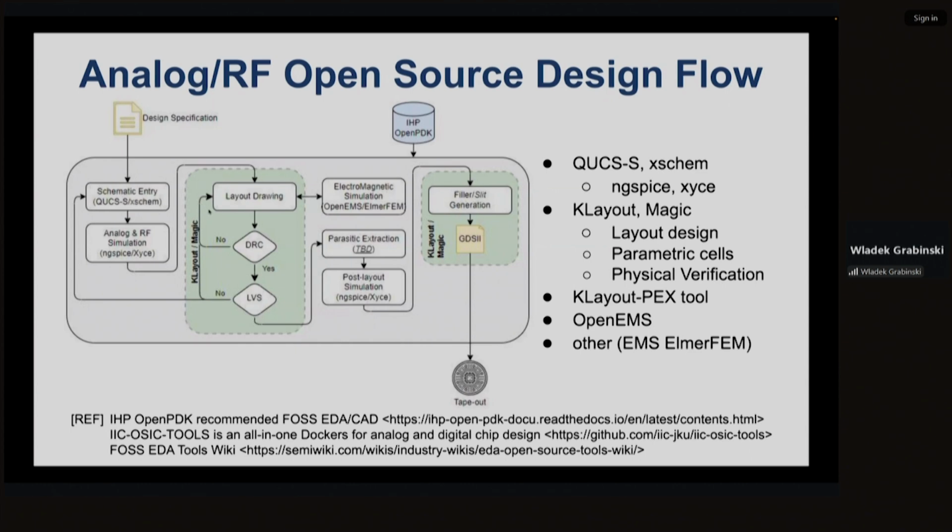If you need something more specific about your RF passive components, you can access openEMS. It's an open source electromagnetic simulator, fully integrated with the flow for passive component verification, like transmission lines, interconnects, spiral inductors, or integrated antennas.